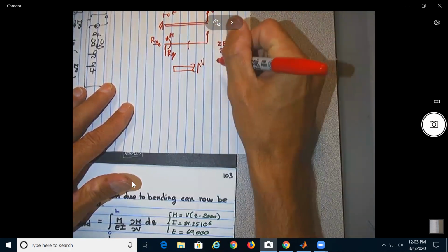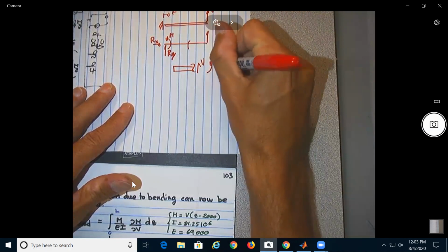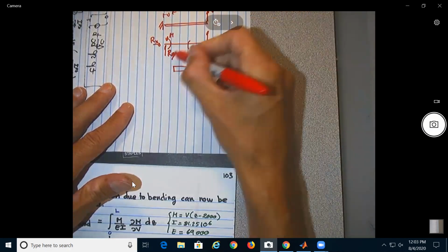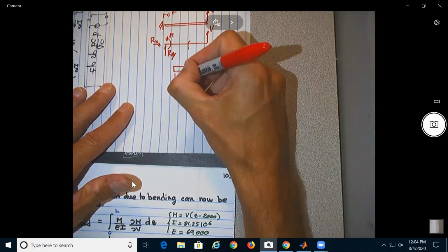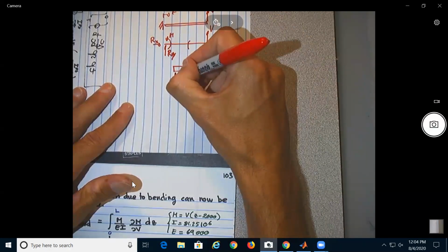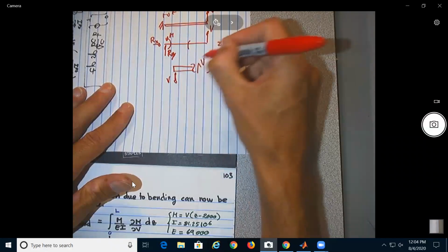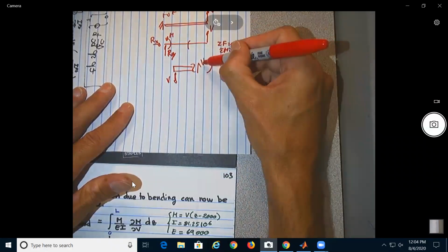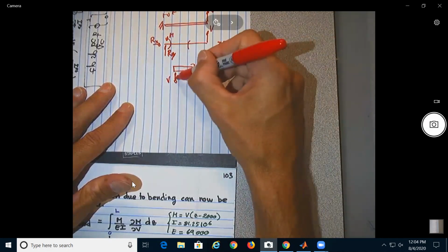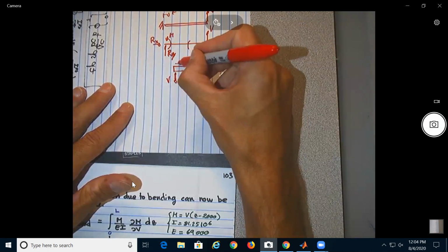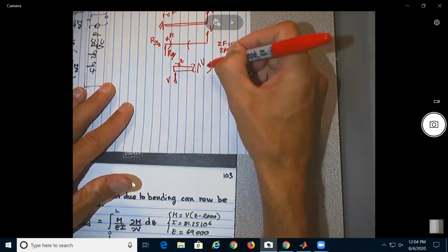This will be V here. This will be the bending moment. This force Ry will be equal to what? To the value of the force over here, no? So really, Ry should be minus V in that direction. So you see that the V should be equal to V over here, no? Ry, and the bending moment will be equal to what? V times Z, okay?